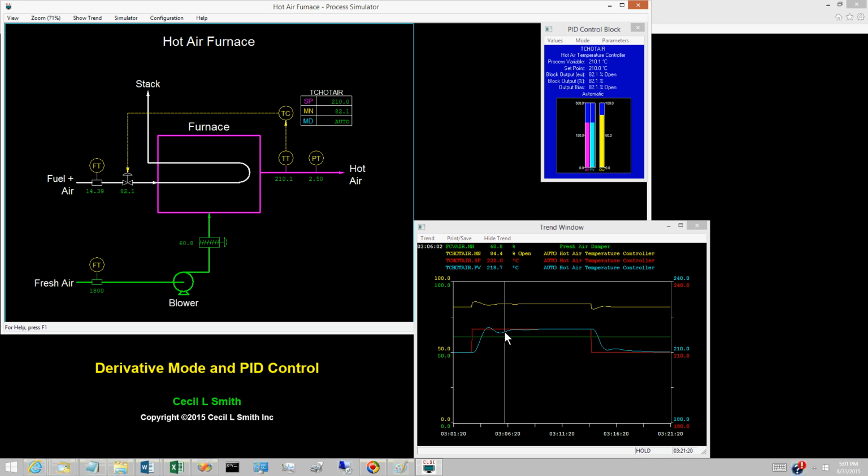At the line in the sand distinguishing stable loops from unstable loops, the oscillations neither grow nor decay. How near a loop is to the line in the sand can be thought of as the loop's stability margin, or margin of stability. The more rapidly the oscillations decay, the greater the margin of stability.